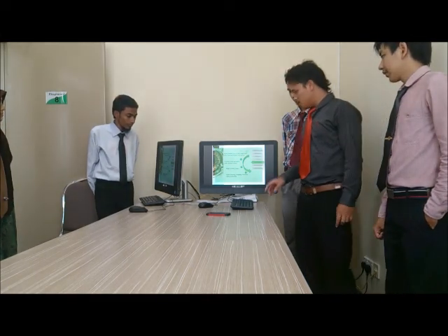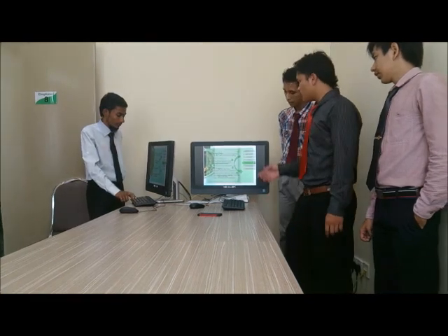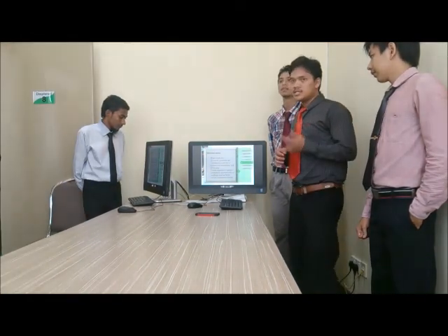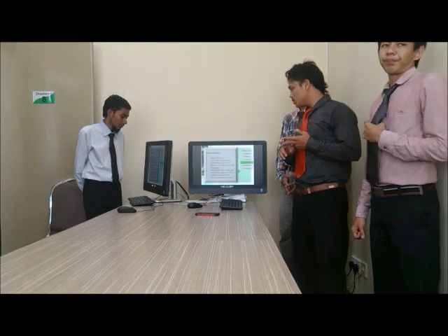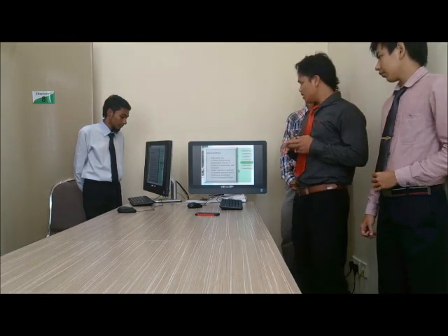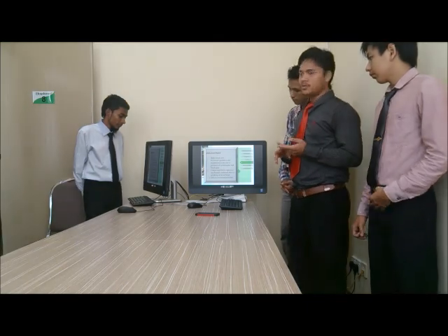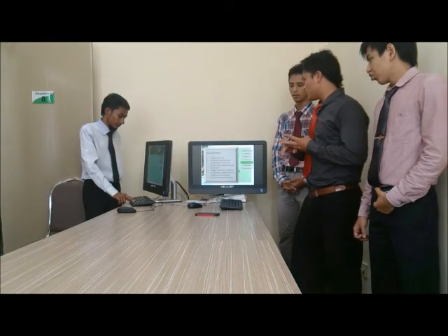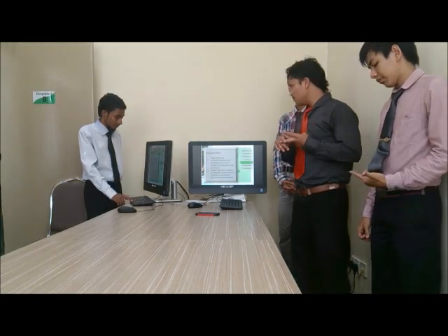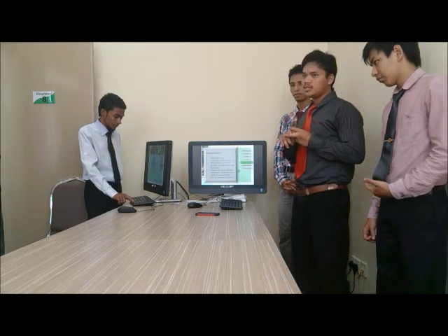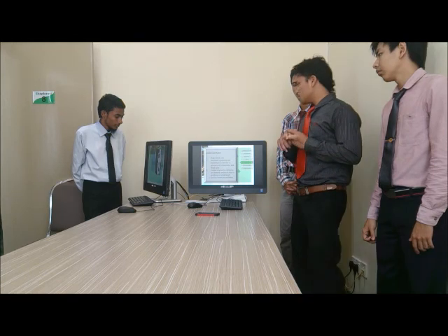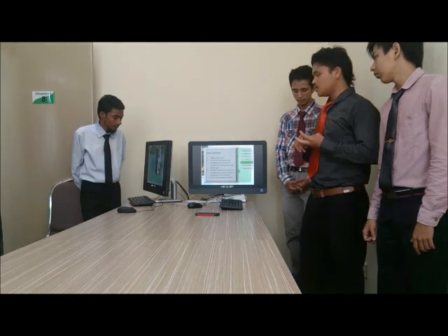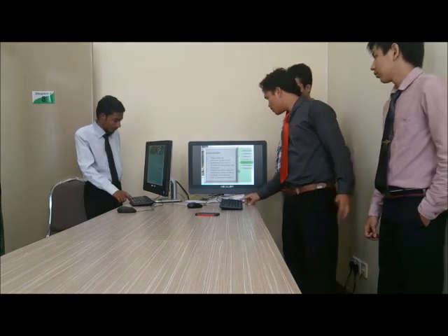For the disadvantages: high initial cost, and increased operation and maintenance cost due to the presence of the commutator and brush gear. It also cannot operate in explosive or hazardous conditions, because sparking occurs at the brush and can result in commutator failure.